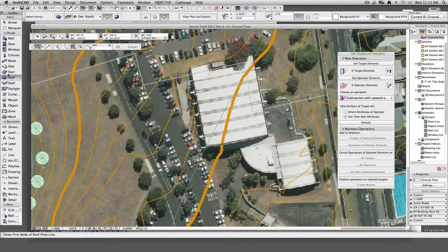Normally we would use the roof tool, however you'll notice there's no curved roof option in here. So it's called a shell. There's lots of options with the shell. I might go over them in a bit more detail with the next assignment. But at this stage, we're just going to do a very simple shell. So I'm just using this first option here, and the first option here, which looks just like the roof that we want to draw, in fact. And I believe it's length first, then width.